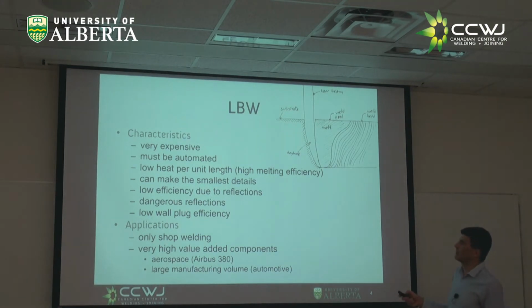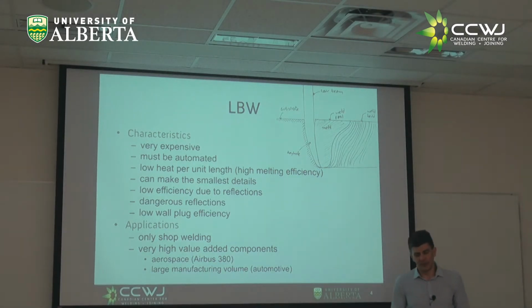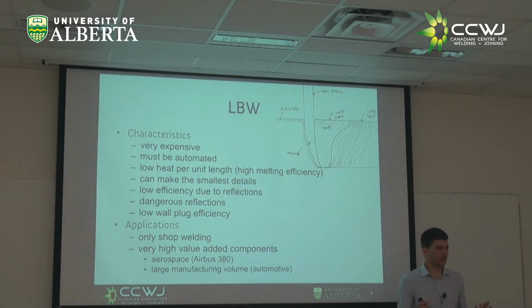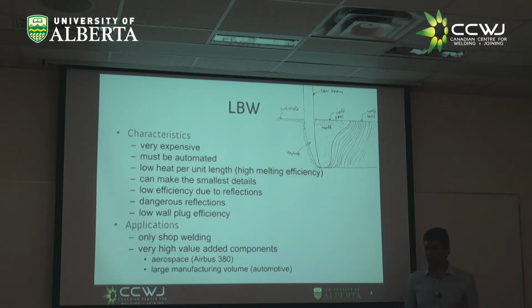Right? So it's expensive. Now, because when we are focusing it, it is a tight spot, it must be automated. There is another reason why lasers must be automated. Not only that it's difficult to keep track, you can say, okay, I'm going to defocus my laser and have a spot that is broad enough to be similar to TIG or MIG or something like that. Yeah, but how about reflections? One of the many difficult things with lasers is reflections, right?